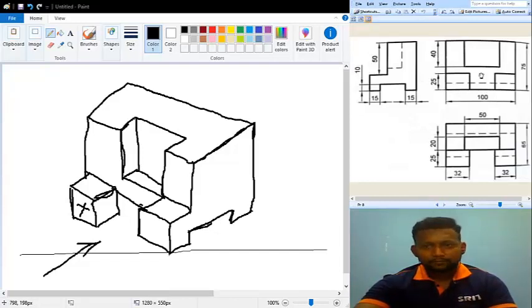And this dotted line over here, this is not completely dotted. From here to here it should be dark. Okay, by mistake it is made dotted like this. So this particular line which is going in this cut portion, inside this particular block, will be dotted. Once it comes out over here like this, it is dark, but it is by mistake shown as dotted lines here.